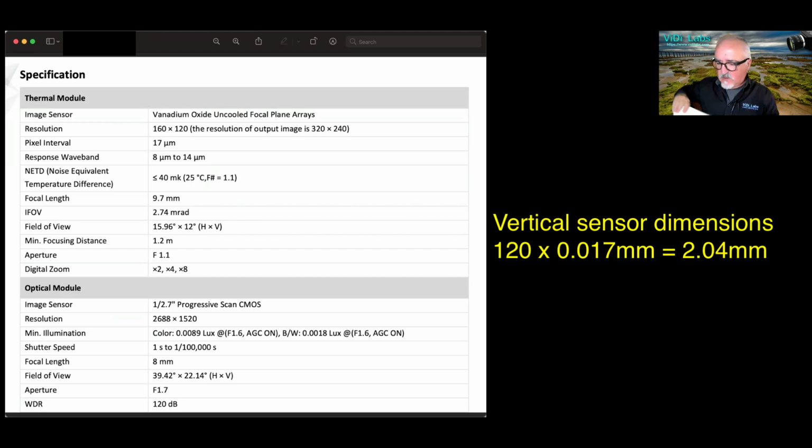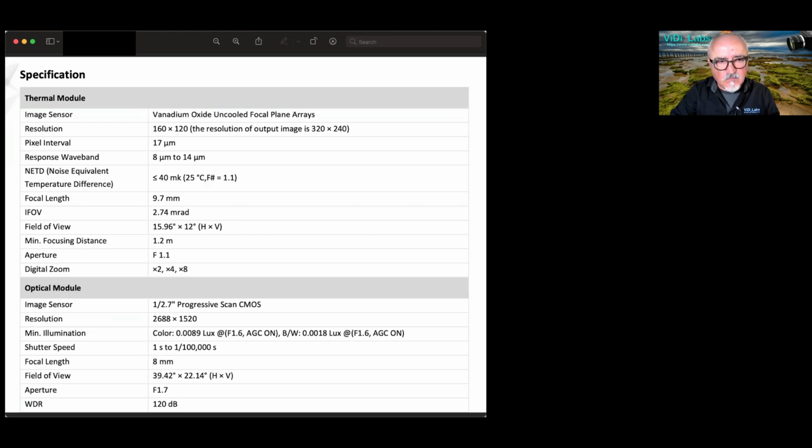So let me now turn onto the, and just notice here that we've got focal length on this particular example 9.7 millimeters. You obviously would have different thermal sensors with different focal length lenses. You have to know what you're ordering, but in my case what I'm showing here is just for the purpose of calculation. That's just to show you that the ViDiLabs calculator can calculate the angles of view of the thermal camera, which is completely different than what you see here with the visible. So don't worry about them being so different, because as I said, they are being then overlaid artificially by the actual camera if you wanted to, depending on the camera model. So let me switch now to the actual